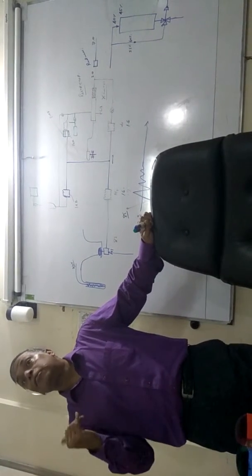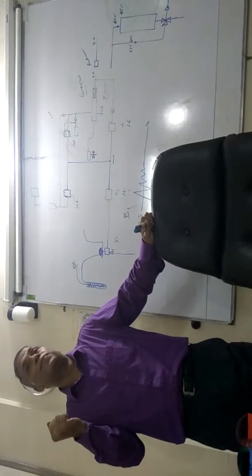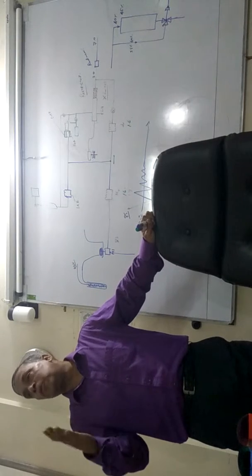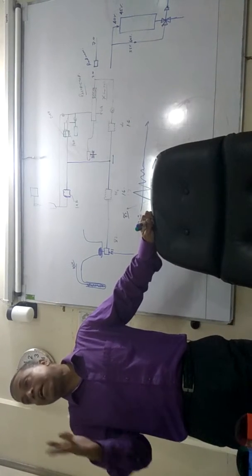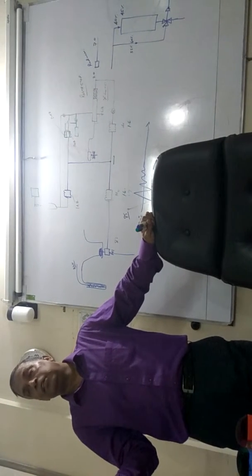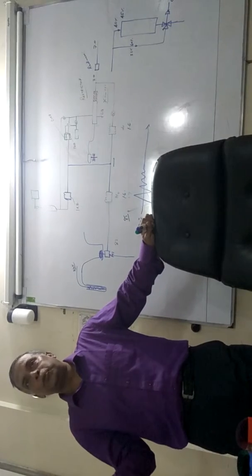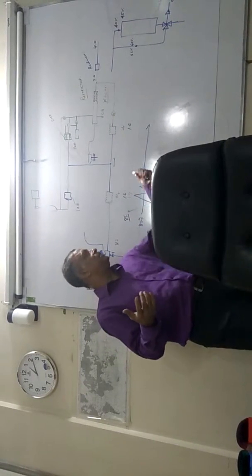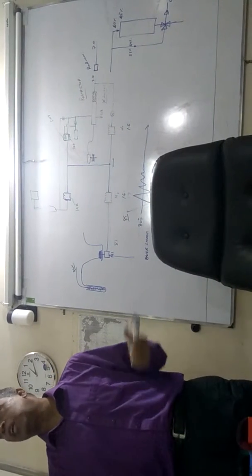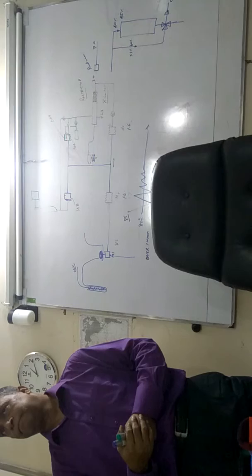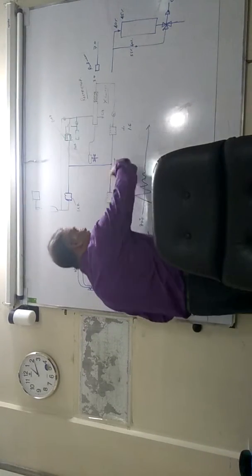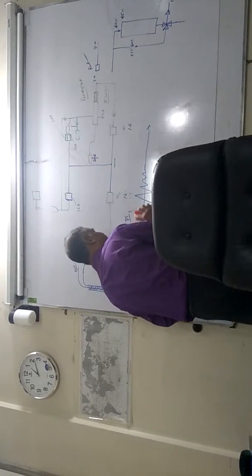Okay? The controller's corrective action is so fast that it doesn't stop on the desired value and creates a deviation on the opposite side. This is called overshoot. And when that happens repeatedly, this is called hunting. Repeated overshoot is called hunting. Okay? Right. So this is the problem with our controller.